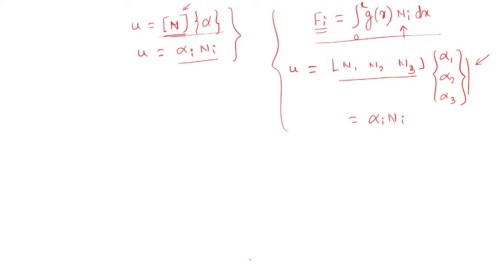Can you explain in short how to calculate the M matrix for a transient problem? Yeah, Dilip, I think I have explained it in detail in the literature. Please go through it. As I said, if you look at the mass term, in say an elasticity problem, it will contain density and some shape functions N i and N j, over the domain.